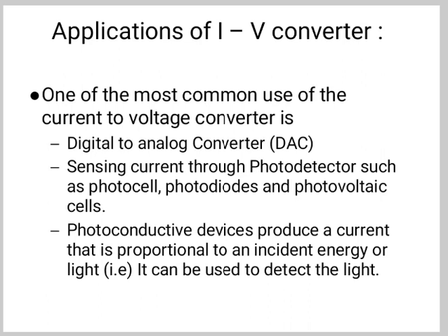If we use nothing but a resistor to perform current to voltage conversion and then connect a load resistor across the current to voltage resistor, then we have two resistors in parallel and the gain becomes the equivalent resistance. So if we use a large resistor to achieve high gain, then connect a much smaller load resistor, the gain decreases dramatically.